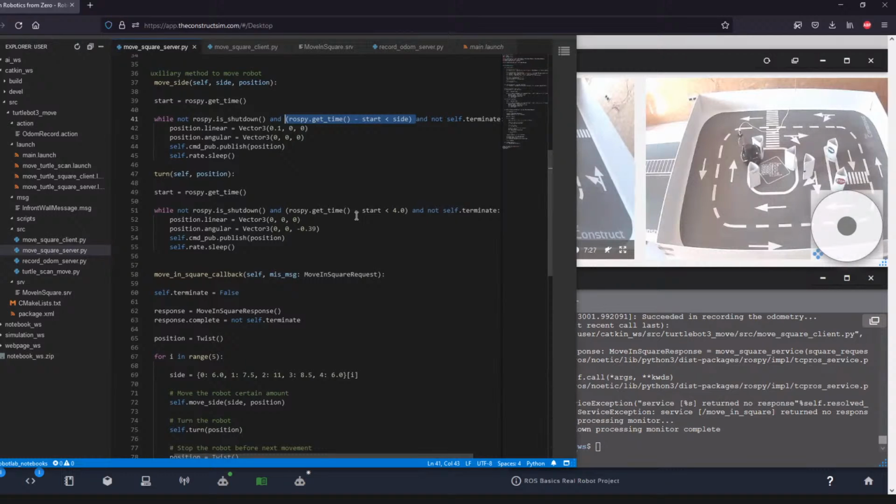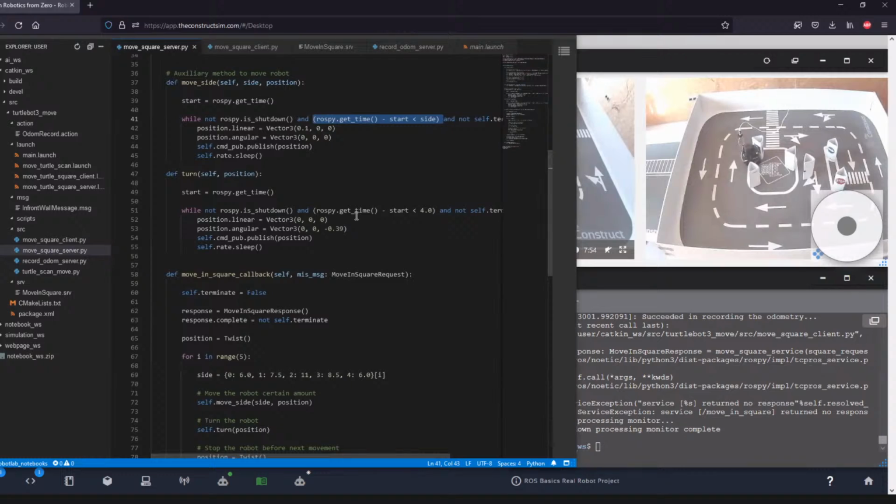Or I remember one of our students looked at a range of the laser scan and waited until it repeated itself, like 90 degrees later. So when the laser scan kind of shifts by that amount, assuming nothing is changing in the environment, okay, that's really smart. That was just another way. But yeah, as you said, using the position and the angular velocity and checking that continuously, that way you could also do it.